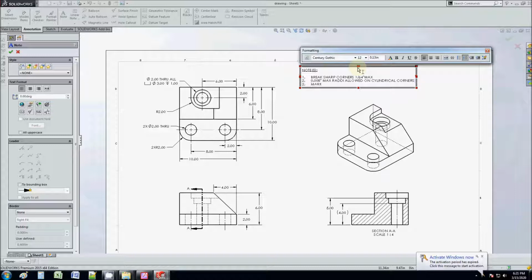Sometimes I like to mark the part number on the part, and I usually put a note where I want it marked, and I even model the location and the mark that I want, print number ABC or whatever. Sometimes I set this as optional though, because a lot of times I'm in a rush and maybe the shop doesn't have a laser marker, so that one's not too critical.